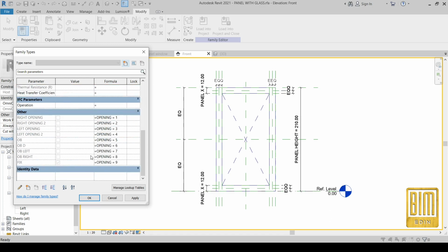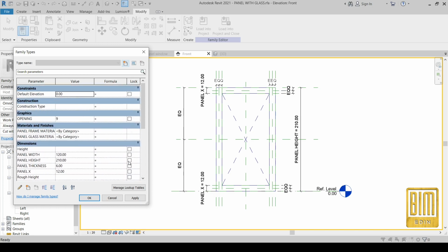And this is the most important parameter for solving the mismatch between Revit window families and legends. Now, changing the values in this parameter here, we will change the opening directions at the same time in the project and in the legends. The changes in the project will follow the changes in the legends, or I should say the opposite: the changes in legends will follow the changes in the project at the same time. You understand?